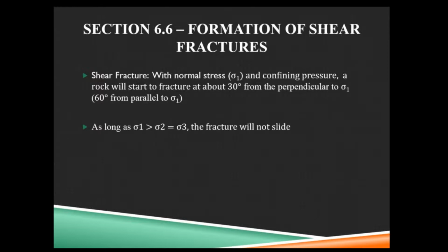And this will happen as long as sigma 1 is greater than sigma 2 and 3, and especially if sigma 2 and 3 are equal to each other. The fracture will not slide if this happens, if 2 and 3 are precisely equal. But the crack can grow if the shear stresses are growing, then we'll get displacement.